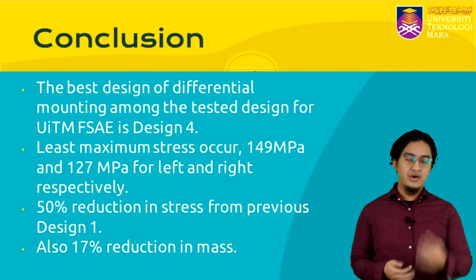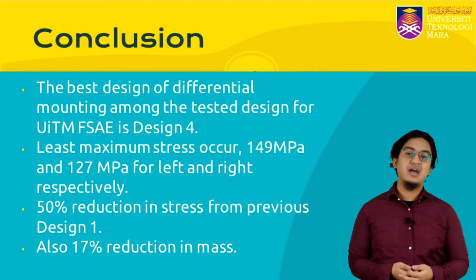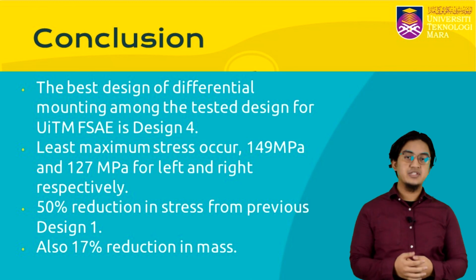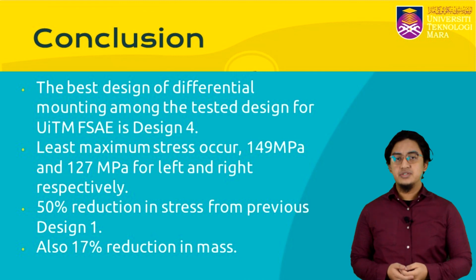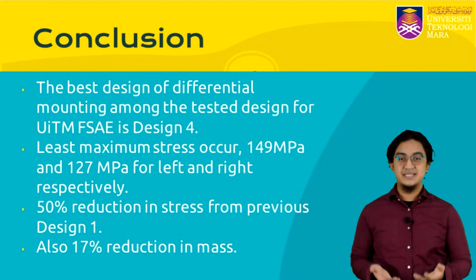So, in conclusion, this project successfully discovered the best option for the differential mounting among the 4 tested designs, which is design 4. This is because design 4 has the least maximum stress occurring on it, which is 149 megapascal and 127 megapascal for the left and right side respectively. The design also reduced the mass by 17%.